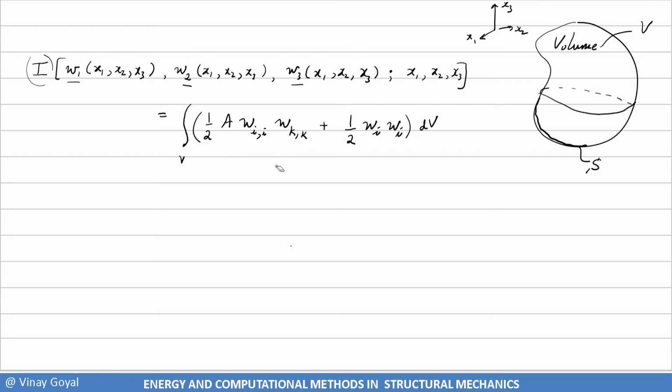And so what we need to do now is determine, actually, let's just add that in. So minus b_k w_k dS. And b_k is only specified on boundary S1. So say this is a volume V, the surface S is made up of S1 and S2. And I'm only applying on part of the surface this loading quantity.